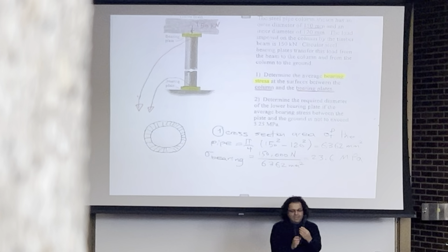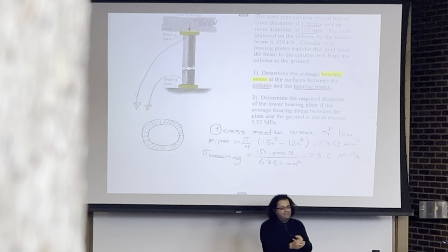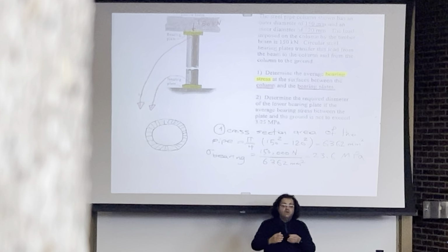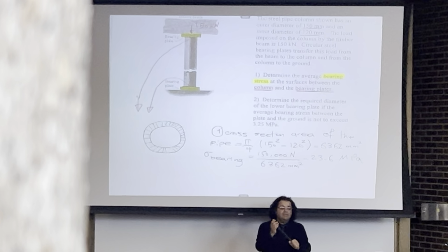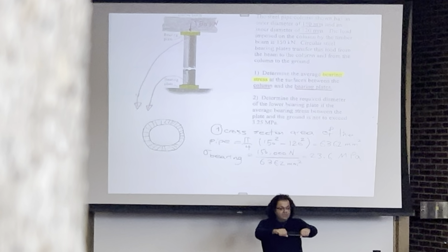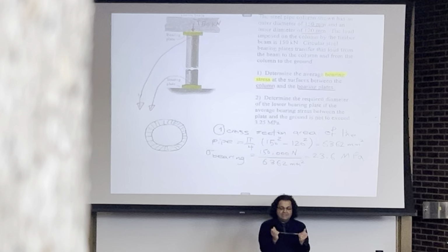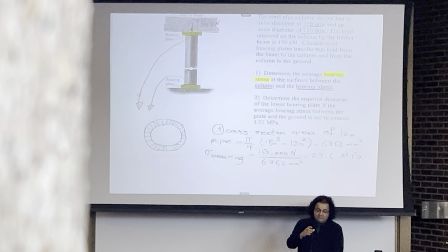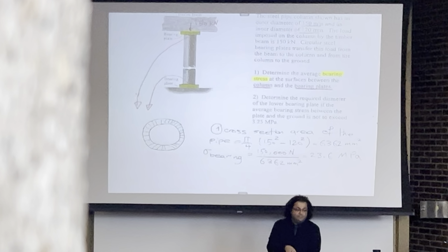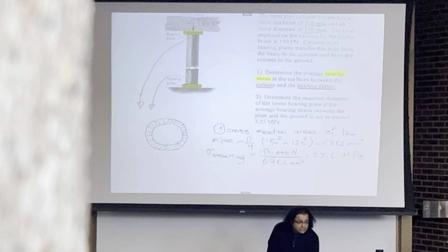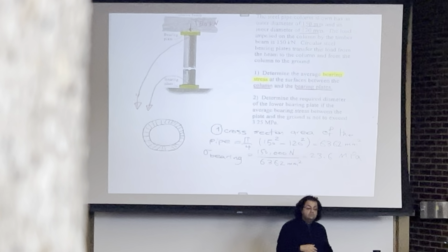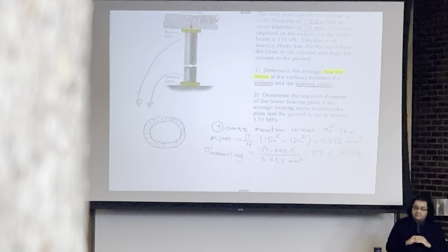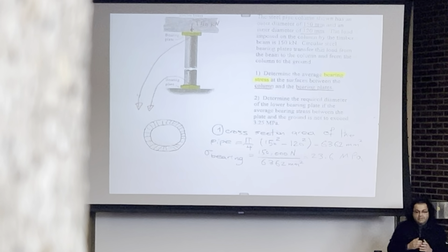Because you agree that we can simulate the cross section with a rectangle where one side is very long. I think none of us can bend the ruler in this direction, but we can easily bend the ruler in the other direction. So if it is used as a compression member, it is susceptible to buckle in this direction easily with a very, very small load. Definitely in the design of a column, the height must be considered. I'm happy that you asked this question.